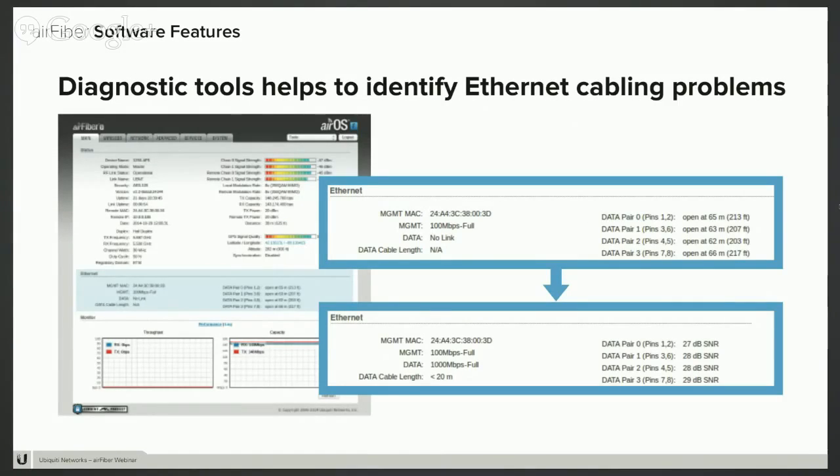On the cabling side, one of the things we've learned is that when you look at a large network, one of the most common problems you find turns out to be issues with cable. And unfortunately, running long runs of outdoor cable up and down towers is no different. So what we've done is integrate a time domain reflectometry system that actually measures and rates the quality of your data link cable.